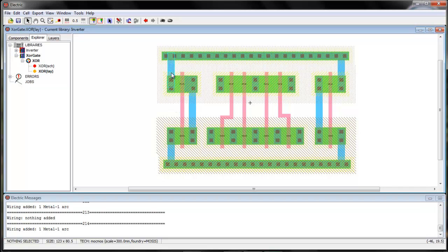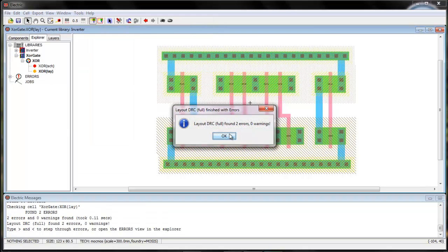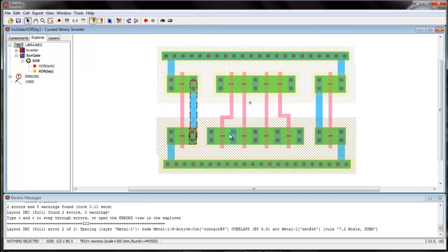Suppose my A is this one. So okay, let me check this. Can you see this dark line here, which means while connecting I just made an extra connection or something. Let me delete this. Can you see this blue? Yes, this shouldn't be here. Just left click, right click. See, so you can just click on this and delete this. Check for DRC errors at every step so that you don't have any errors further.